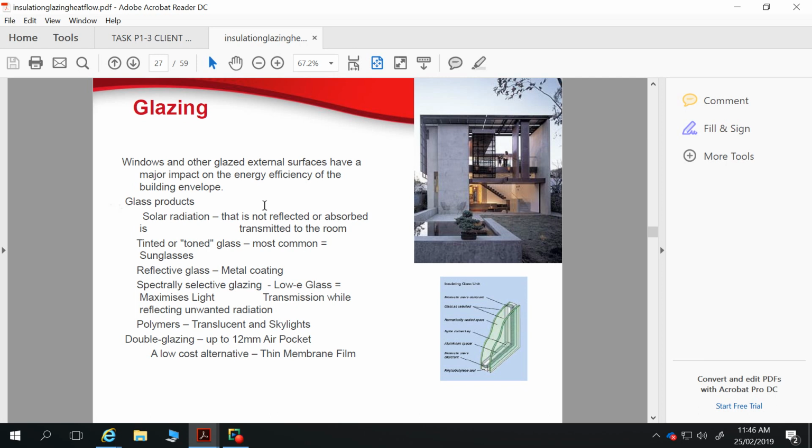So talking about our place on the esplanade, we want a low solar heat gain coefficient. If we were putting the glass on the northern side of our house to get that warmth in, to get that solar radiation through, we'd want a very high solar heat gain coefficient. So SHGC can be a benefit. You can choose low or high depending on your location within the house. Like emissivity, your low E glazing, that's generally a good idea anyhow wherever you are. Helps maintain that temperature in your house, gives you far more control over that.